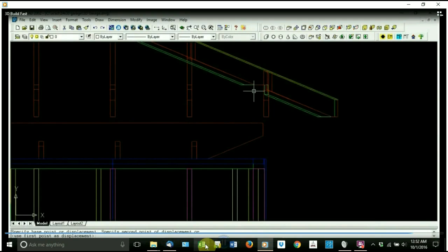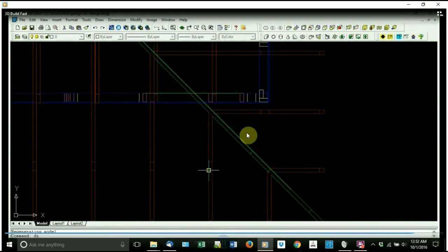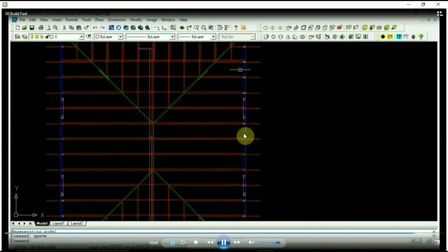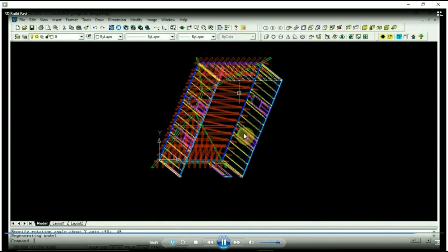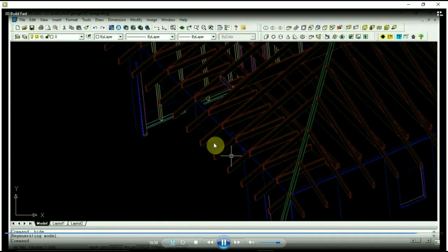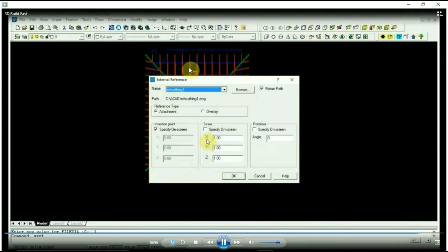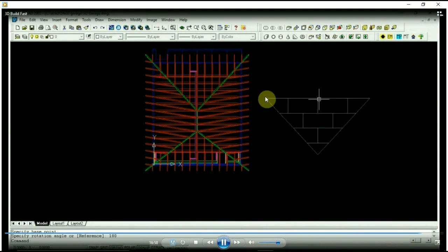Now in this view you can see that the main joists are upside down. I got the main joists upside down. You can see they're flipped. So once I get the sheathing and everything put on, I'm going to go into that joist program and I'll end up mirroring those really quick. So right here I'm going to put in the sheathing. So I just rotated the building 22.619. This face up here is perpendicular to me. I'm going to place this sheathing right on top of that.